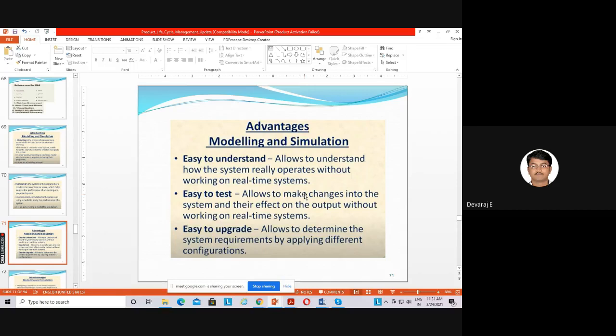In practical cases, 99% of all materials will have crystal imperfections. But when you do it in ANSYS or a numerical method, it assumes the atoms are arranged neatly and homogeneously inside the material, so it will give accurate results, depending upon the mesh size you give. It takes directly the assumption that the atoms are arranged neatly.